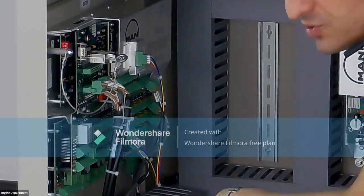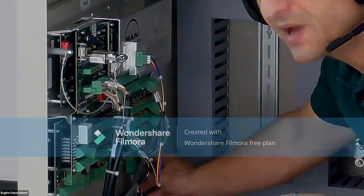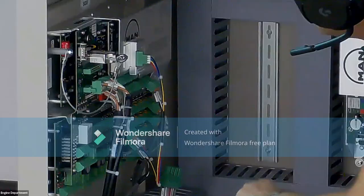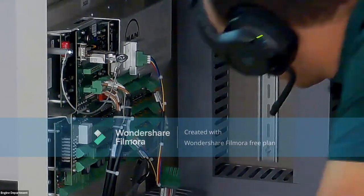After you switch off the breaker, disconnect the power supply plug. So this is the power supply plug, disconnect it from the MPC. Disconnect the network cable.